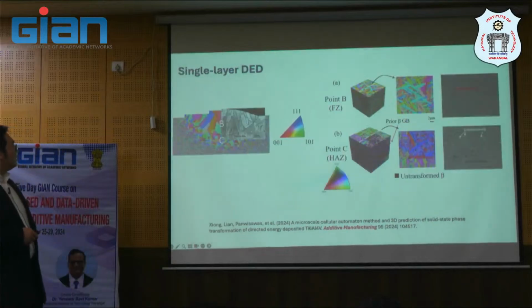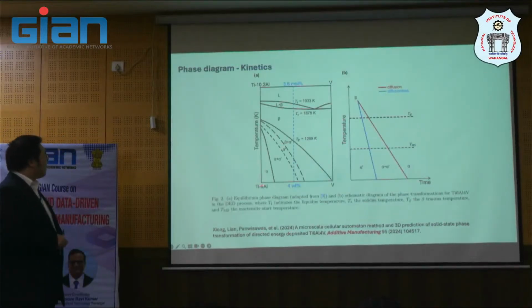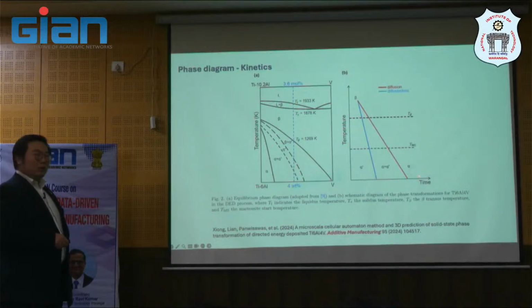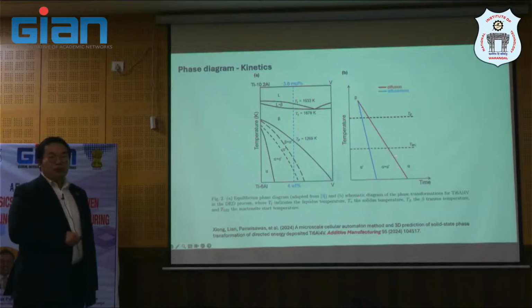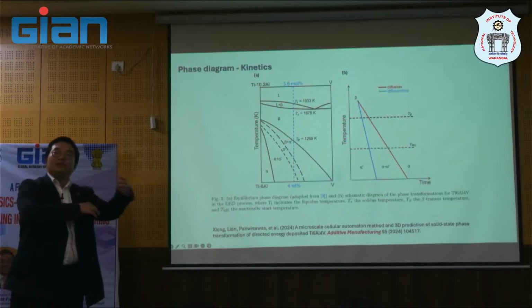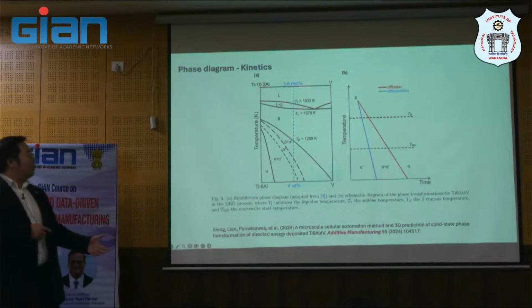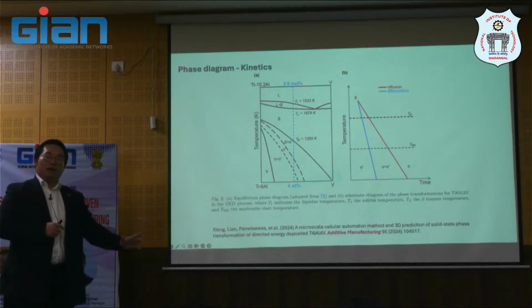So that is the conceptual diagram that we try to draw here. You will not actually go through this pathway easily. In your alloy design, you may need to adjust your merit indexes, or basically the criteria that you use, considering these kinetics that are induced by the AM additive manufacturing processes as well. And this will feed into the alloy design or data-driven machine learning framework that I mentioned earlier. And this is how we feed back or improve the model to design a new product.